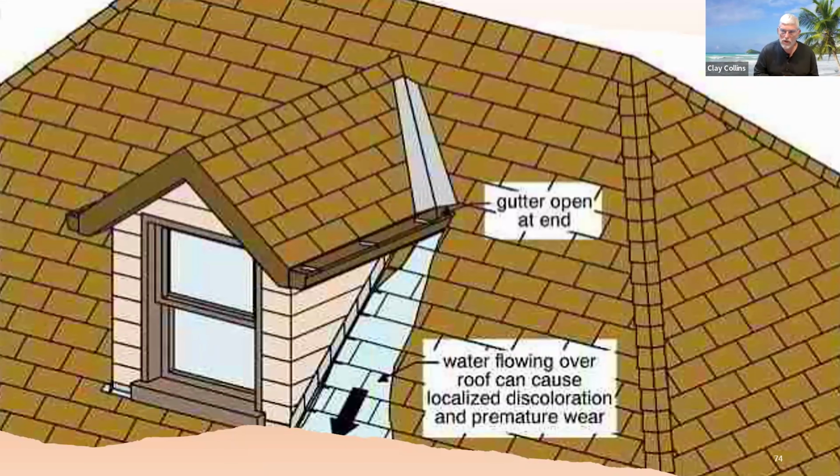Now, this was the question asked a while ago. Manufacturers of the shingles say don't do it. Their installation instructions say don't do it. And I report it every single time as a deficiency. But the truth of it is that I don't expect anybody to fix it, because the trade-off for doing it correctly is more downspouts.